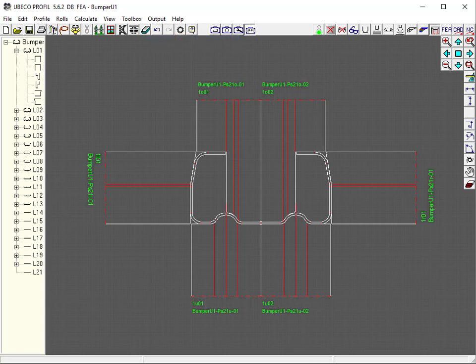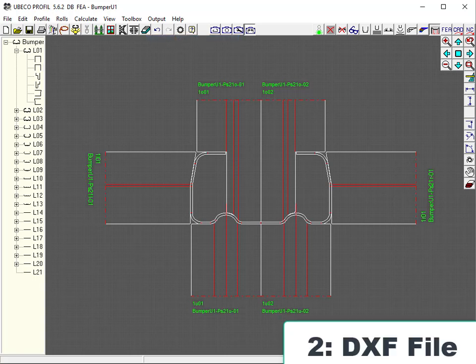Output drawings to NC creates DXF files of the rolls. These files can be imported into a CAD CAM system for creating the G-codes in this specific system. Normally, CAD CAM systems have a specific post processor for each machine control.